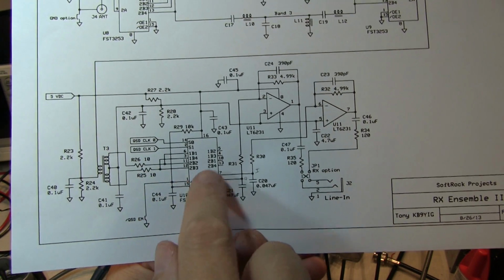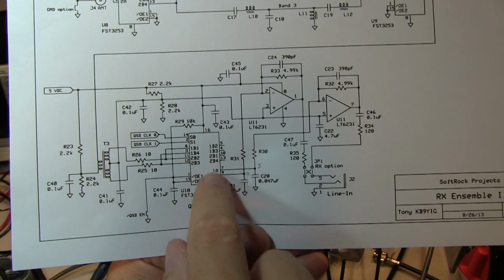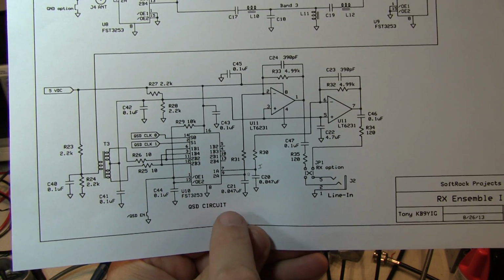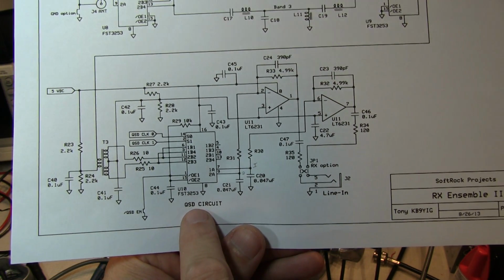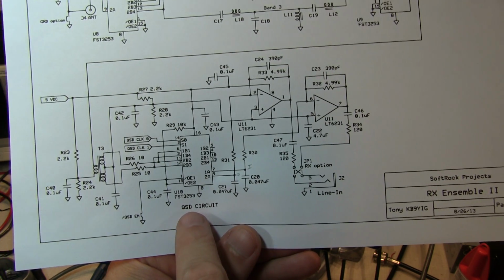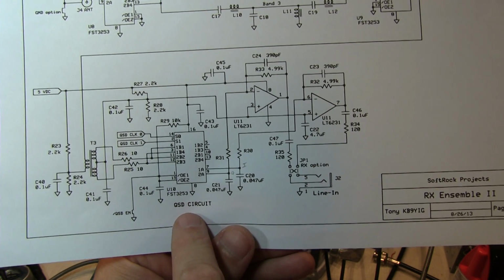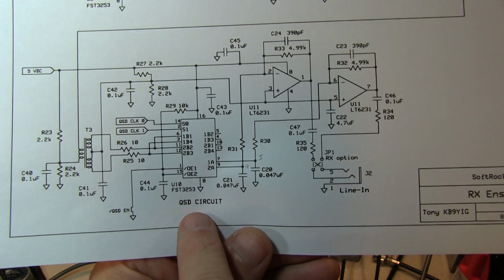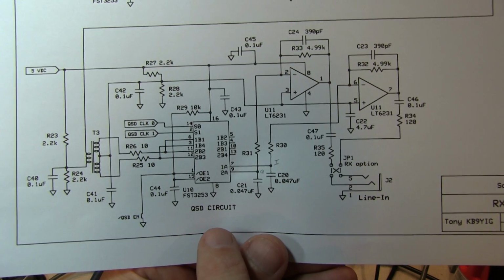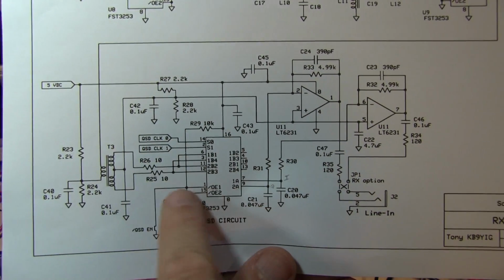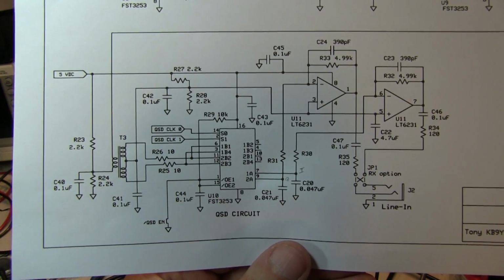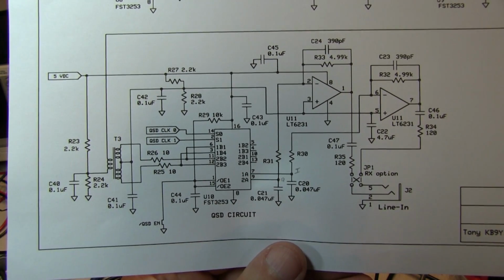That balanced output then goes into another one of those CMOS switches, and this is configured to perform the Quadrature sampling detector. You can also think of it as a Quadrature mixer, and it's also known as a Tayloe detector, after Dan Tayloe, who invented this circuit architecture and actually patented it. To understand how that detector works, it helps to draw a little bit of a simplified schematic. So let's look at that.